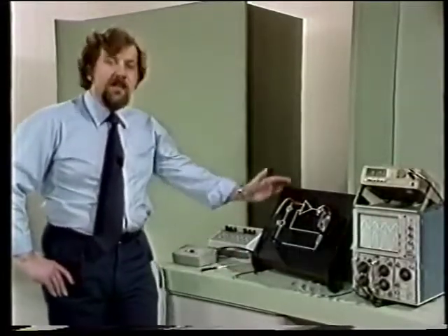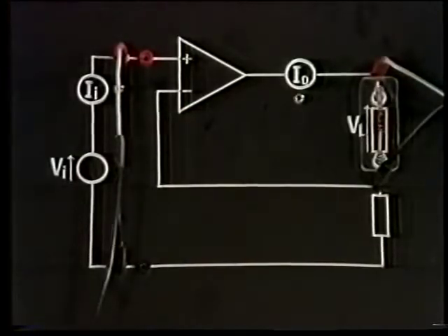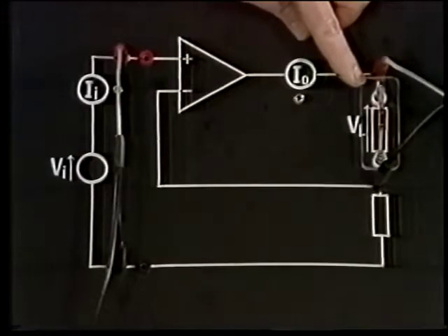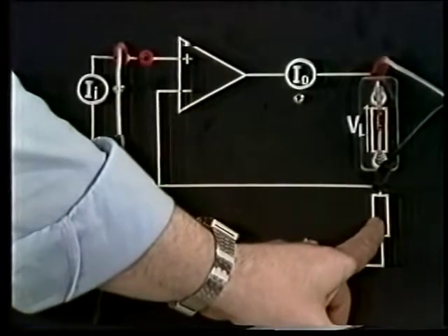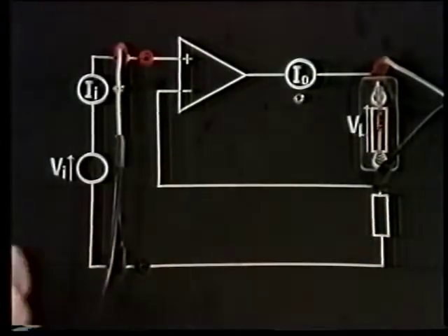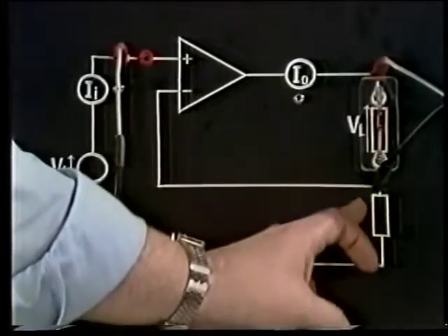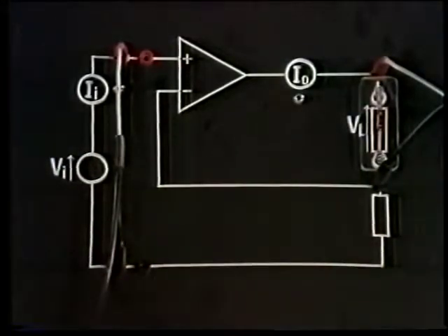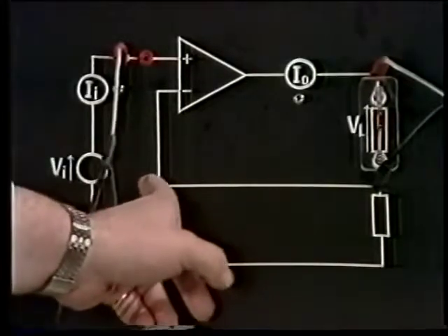Well, now for a different kind of amplifier. This is the current-derived feedback circuit described in the unit. You'll remember that I'm using RL as the load resistor. It's the voltage across this second resistor that's fed back. So the feedback voltage is proportional to the current through this resistor, and hence to the current through the load. This will always be true provided that the input current drawn by the amplifier is negligible.